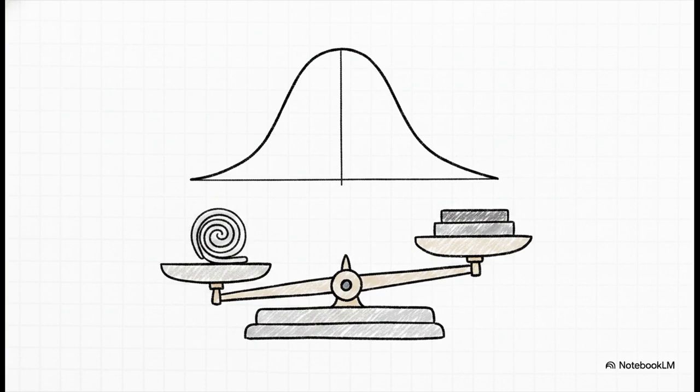Since a distribution transformer spends most of its life lightly loaded, where those constant core losses really dominate, utilities deliberately specify low core loss designs for exactly this reason, even if it costs a bit more copper up front. The golden rule? You always design for the actual load profile.